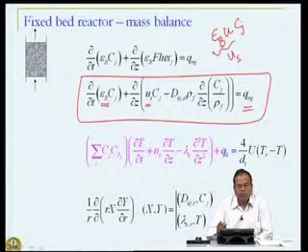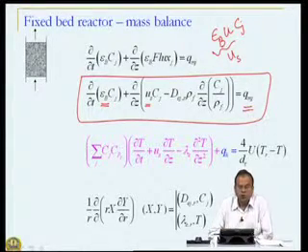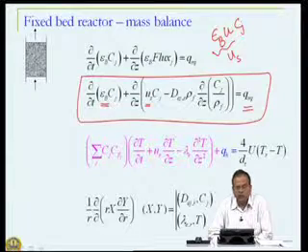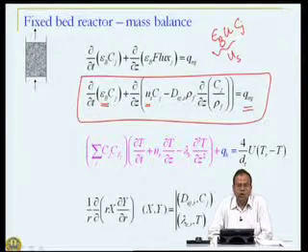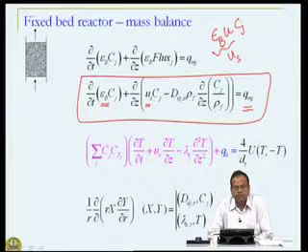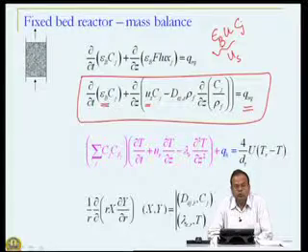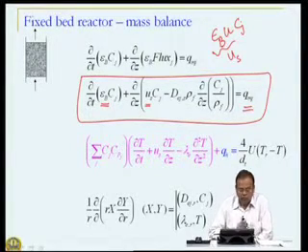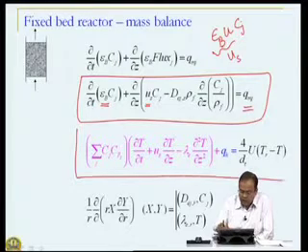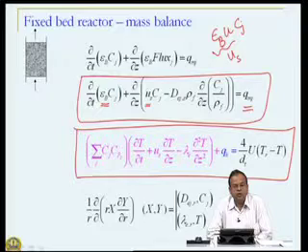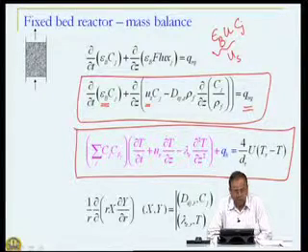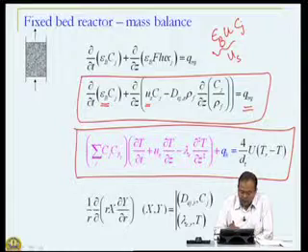rate. But remember, we now have transport phenomena, that is internal as well as external diffusion phenomena associated with the catalyst pellet, that is responsible for telling me what the rate of reaction is. So, I have to make suitable assumptions and put some values for that rate, but before we do that, we will take it that our energy balance will also be similar to that for a tubular empty reactor, with the exception that